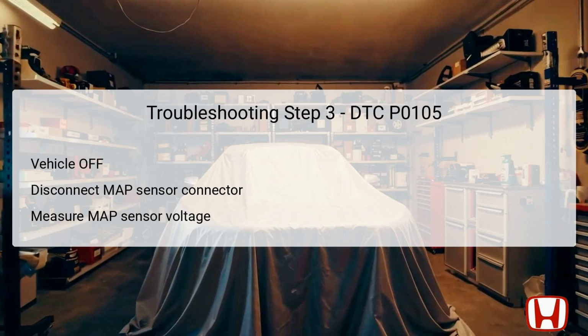the MAP sensor. If the measurement falls below 0.32 volts, the next step is to go to Step 6, indicating that further issues may lie within the MAP sensor itself or the components connected to it. However, if the value is above this threshold, it directs the technician to Step 4 for an accurate assessment of the wiring and connections involved.